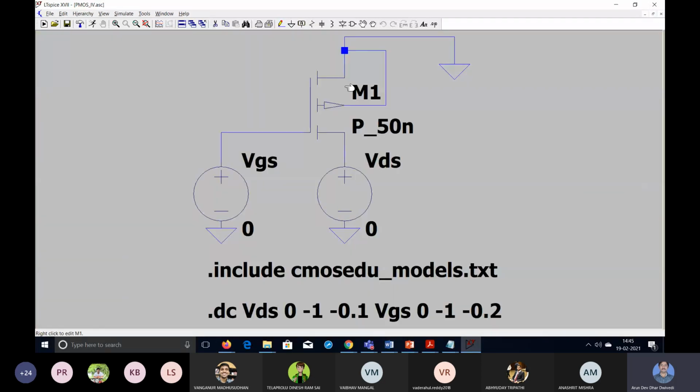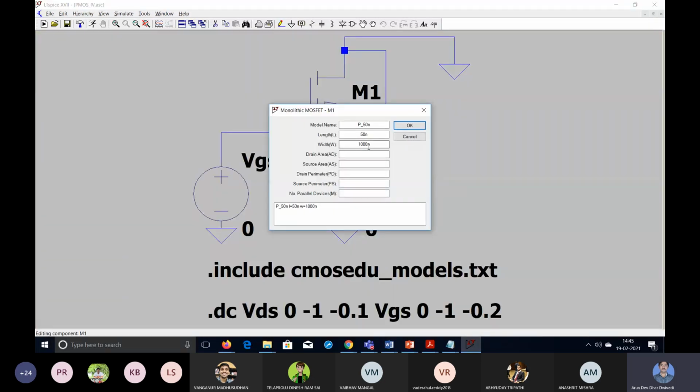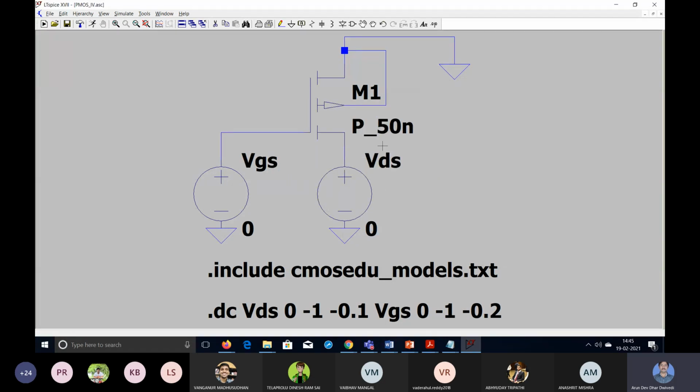So also one more thing we have done, that here we have provided double channel width. In NMOS we were taking only 500 nanometer, or 0.5 micrometer, we can say. Here 1000 nanometer you can give, or you can also give 1 U, means micron. Channel length is same, but width is, oh sorry, you want to double the channel width, so 1 micron, 1 U you can write. It is PMOS, so you can write 1 U. So 1 micron width is given, and also channel length is same. So by that way we are getting the same current and symmetrical. It is symmetrical, but in the opposite quadrant.